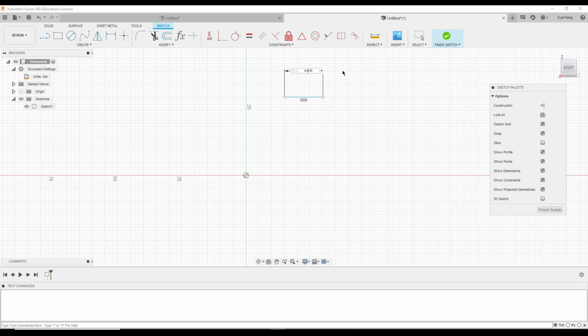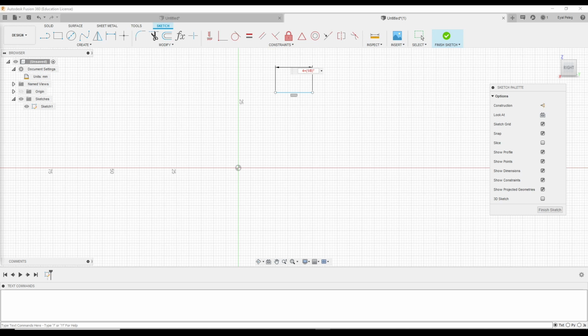Even so, when Jason in the live stream tried to do his 4 and an eighth, he wrote it like this and got an error. So why is that? The problem here is with the parser that interprets the units from this expression. From my attempts to play with it, what I have seen is that the units can only be applied to numeric literals and not to expressions like the 1/8 within parentheses that appears in here. I will explain how to fix this in a moment.